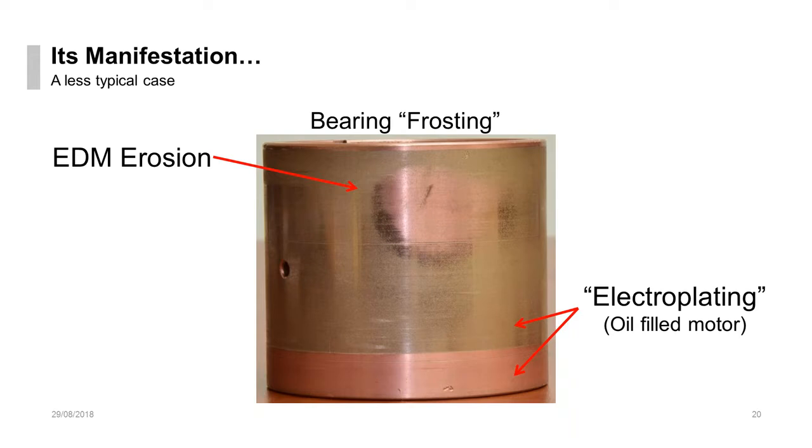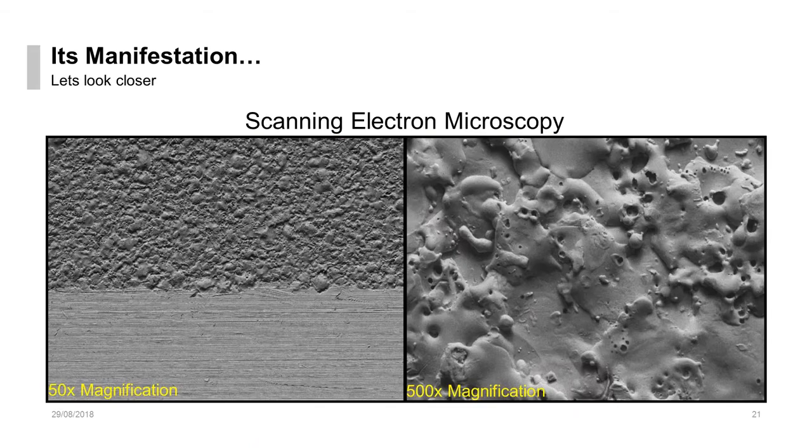What we believed was going on here is that the high frequency content created, again, a non-zero vector sum, which creates a potential, and was actually causing copper plating on what would normally be a very shiny brass colored sleeve bearing. We call this frosting, and it almost looks like it was sandblasted, but it doesn't happen very evenly, only in places that have very tight tolerances.